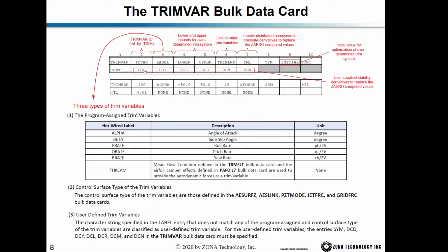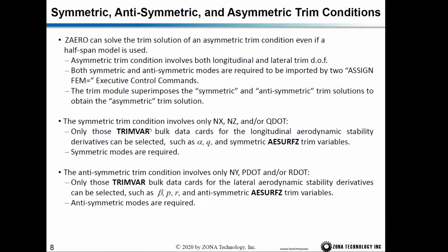So you have to calculate the aerodynamic force and moments about the aerodynamic center with respect to this trim variable. We have three types of trim variables.